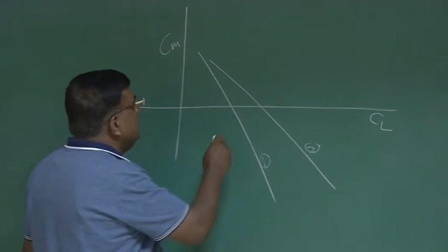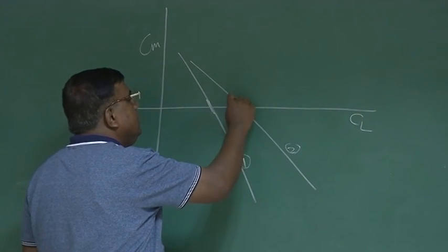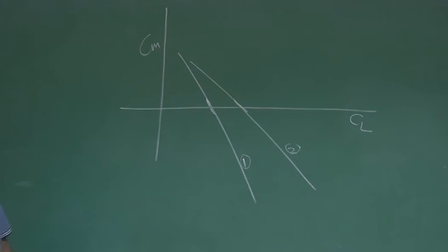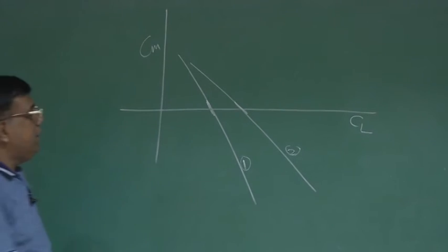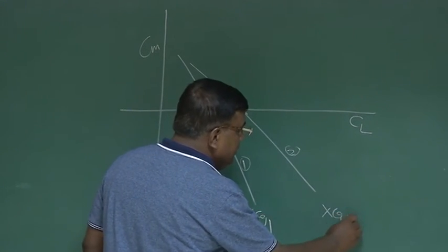You could very well see in case 1 the slope here, and the slope here. This slope is more negative compared to the slope at 2. That means the airplane in the configuration of XCG1 is more stable than XCG2.